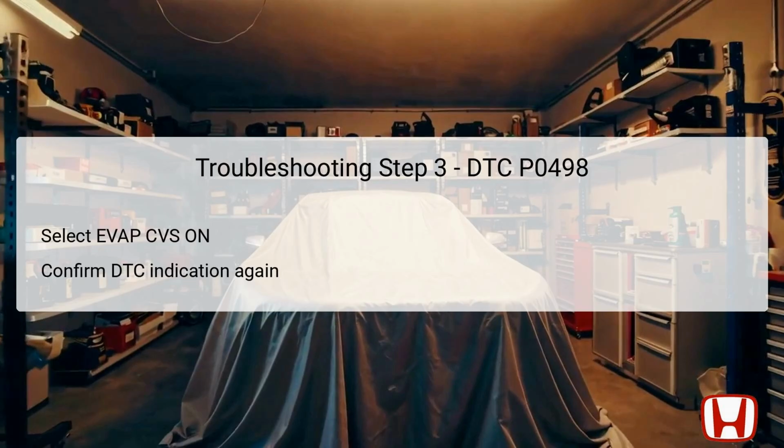After engaging this option, the technician again checks for any pending or confirmed DTCs using the HDS Diagnostics. This is a critical verification step to ascertain whether the previously identified P0498 code reappears during the active test. If the code does appear again, it indicates that the issue persists within the EVAP system, necessitating further inspection of